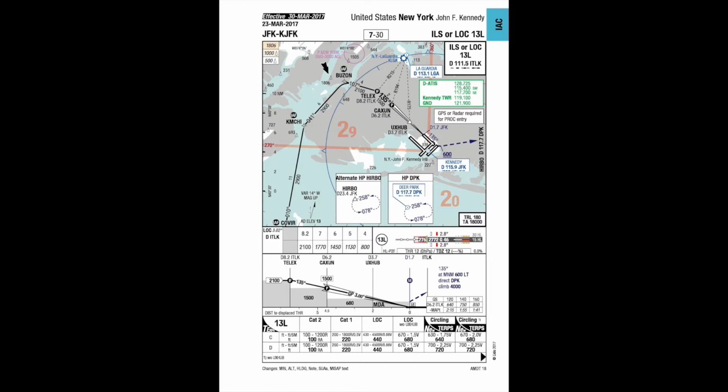The landing minima section of an instrument approach chart shows all procedure relevant lowest permissible landing minima for the approach depicted in the chart plan view. The information is displayed in an easy-to-use table found under the profile of each instrument approach chart. As a standard, Lido publishes minima according to EASA regulations. However, charts which contain minima calculated to TERPs design criteria will be labeled with flags. Straight in and circling will be flagged independently.